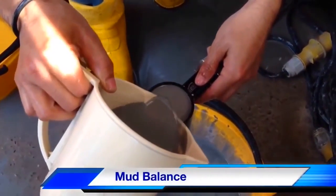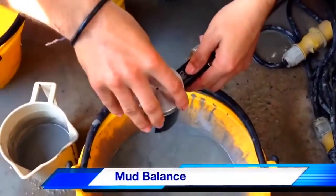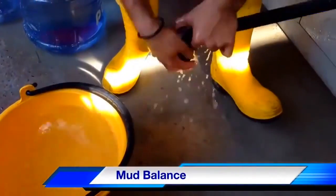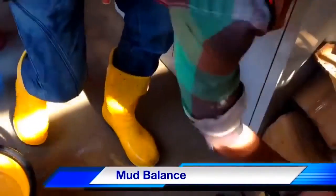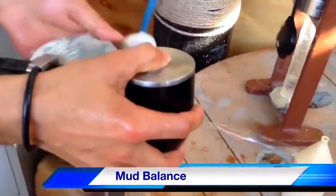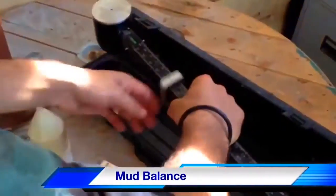The density of bentonite is measured by using mud balance apparatus. Bentonite is filled into the cup and the surface of the cup is cleaned properly. Then the arm with the cup is placed on the balance. The counterweight of the arm is changed until the bubble of the arm comes to the center, and when the bubble is at the center, the density should be recorded. Standard bentonite density values vary from 1.1 to 1.25 grams per milliliter.